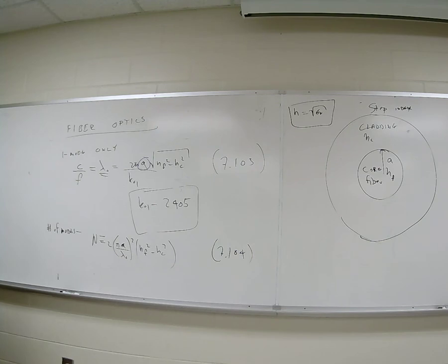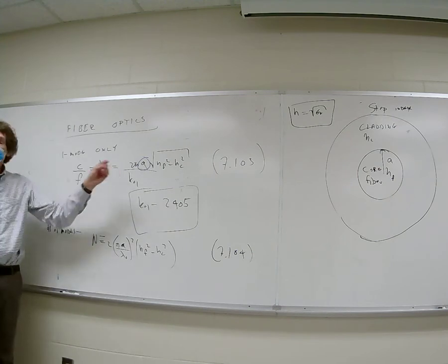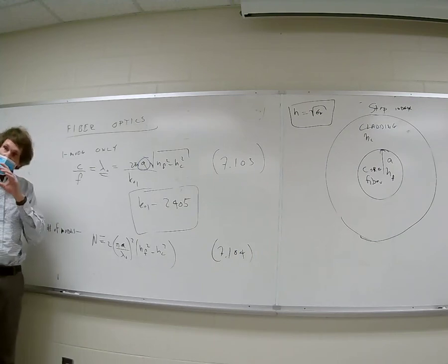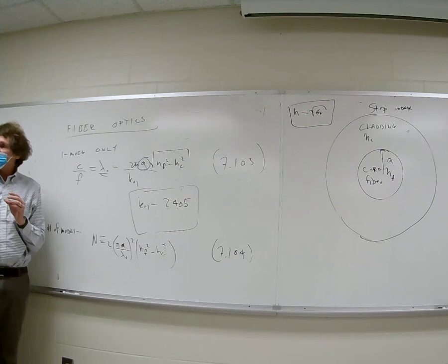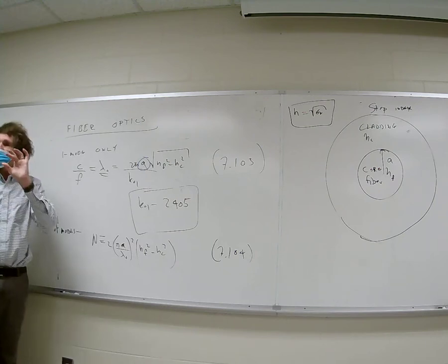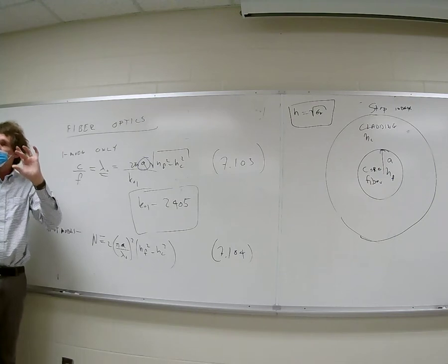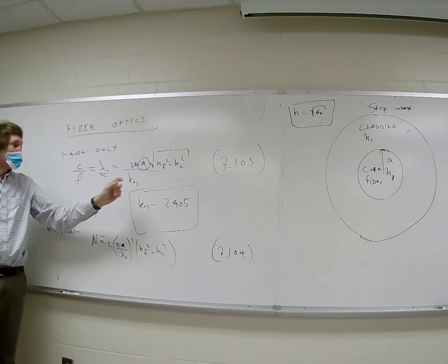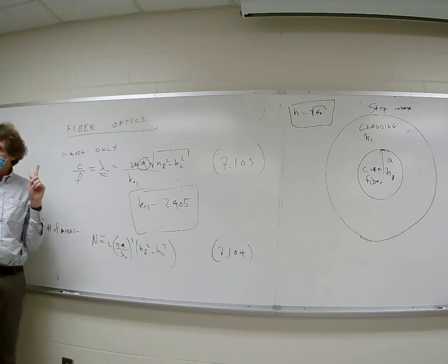If I give you a problem, and I will, after I speak today, I will ask you what the radius would be to allow only one mode, right? Now, the question is, you want to make it just a little bigger than that. Not exactly that, because there's always some fudge whenever you do designs. You're going to get a distribution of widths and stuff like that. So you make it a little bigger than that, maybe 2-3% bigger when you actually draw the die on this. But this is what you design for one mode.